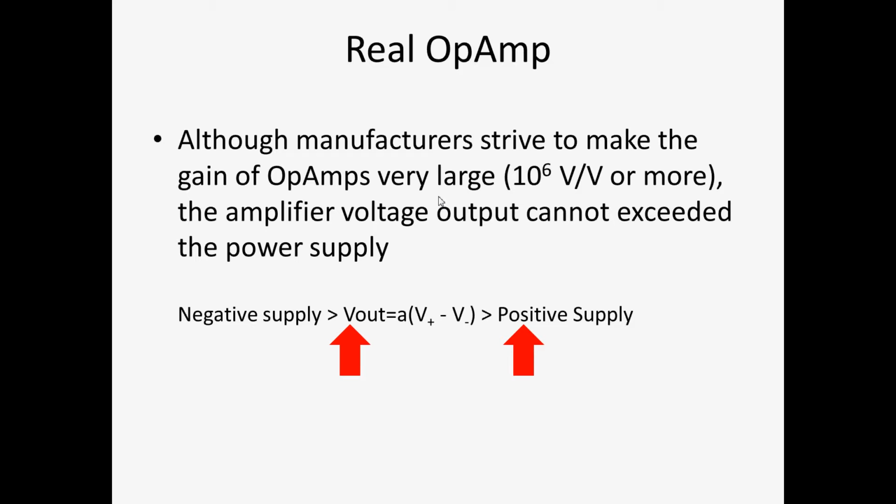In the example I just gave you, a positive voltage supply of 10 volts, but you see in what I plotted that you normally have a positive and a negative supply. That is because our signals sometimes have negative excursions, so we want an amplifier that is able to follow those negative things.